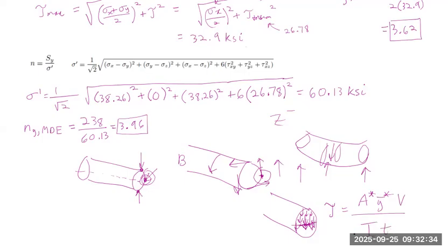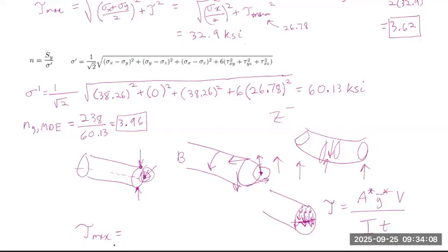However, for these types of problems, we only have to be concerned with the maximum transverse shear stress since we are concerned with the limit conditions, the maximum stress that it is going to have to sustain. So we know that our maximum transverse shear stress for a circular cross-section is equal to, from our equation diagram, 4V over 3A. And again, I think this formula is not on the equation sheet, so you have to memorize it yourself.